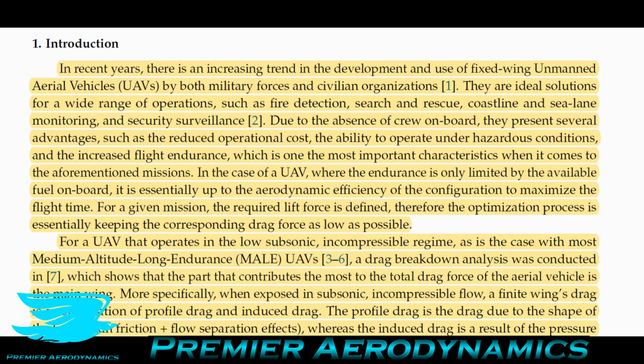So in the case of a UAV, they say, when the endurance is only limited by the available fuel on board, it is essential to be as aerodynamically efficient as possible. For a given mission, the required lift force is already defined. So that means that you already know how much lift you want to produce in the mission profile. So now it's really just a matter of reducing the drag as much as possible to maximize the lift to drag ratio. The lift to drag ratio is a measure of an aircraft's aerodynamic efficiency. The higher this value, the better the aerodynamics is.